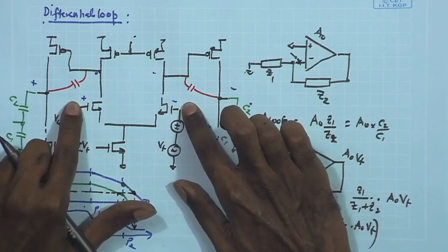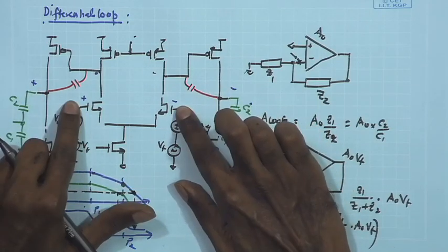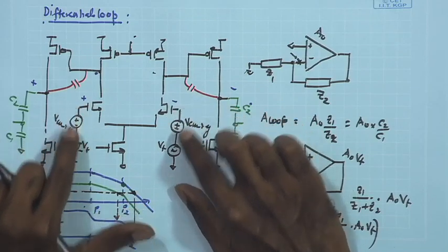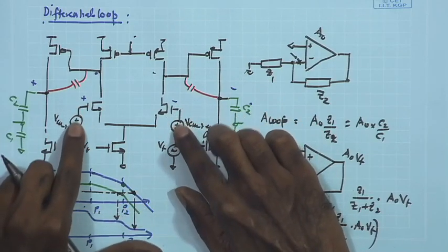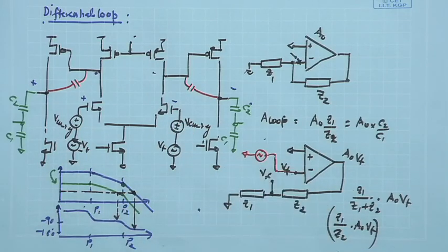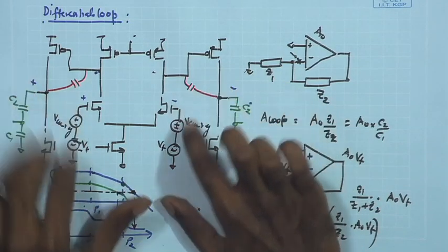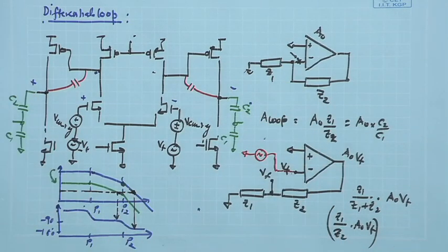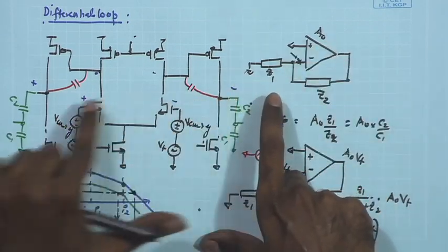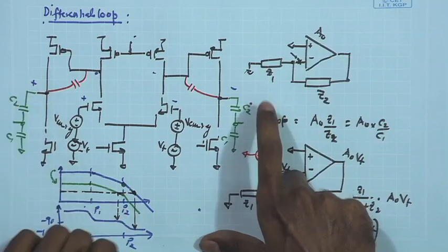The only thing is that if you are getting rid of the resistive feedback for simplicity, this RF that was connected between the input and the output side, then you will have to apply this DC potential over here. Remember, even if you keep the RF connected, like what we have now, if you draw the RF, it will become complicated because you have the plus to minus coming. So, this has to connect here and this has to connect over here for the RF.